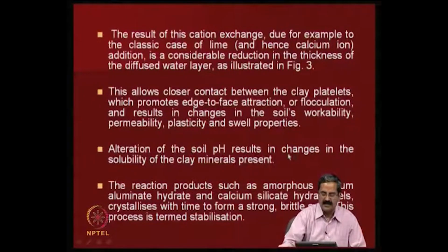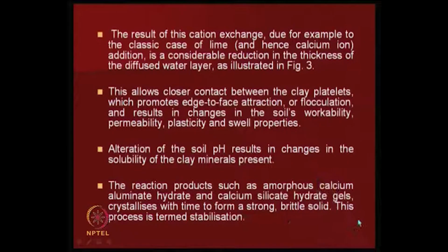Alteration of the soil pH results in changes in the solubility of the clay minerals present. The reaction products such as amorphous calcium aluminate hydrate and calcium silicate hydrate gels crystallize with time to form a strong brittle solid. This is the process of stabilization.